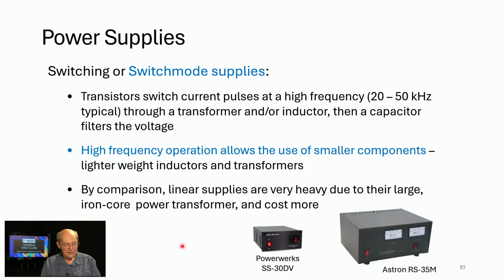So some hams are very particular here. They won't use switch mode power supplies because of that high frequency switching that's happening. And that high frequency switching can cause noise across multiple ham bands. But if the power supply is designed for ham radio use, it can be perfectly clean, as to me proven by Elecraft's recommendation of this for their high-end radios. So they're good to use if they're designed for ham radio use. Much smaller, much less expensive, and just as good.